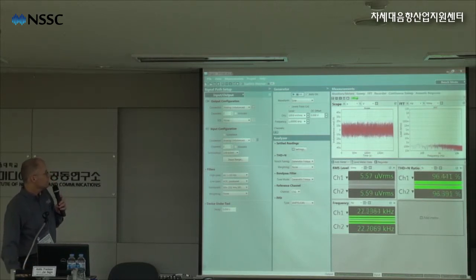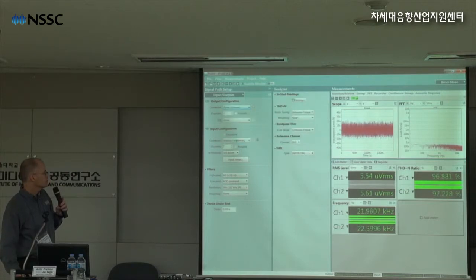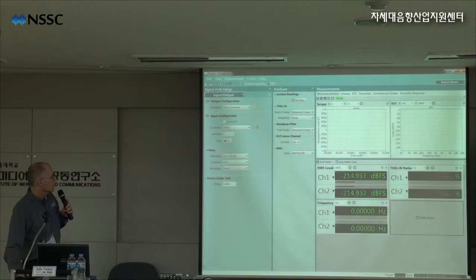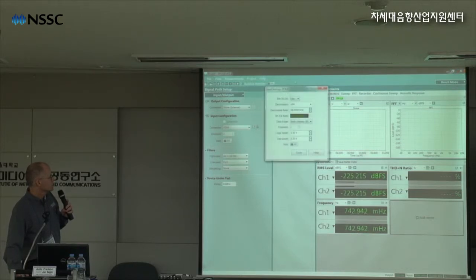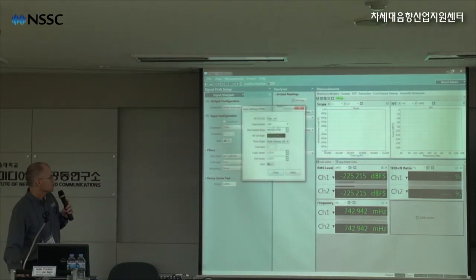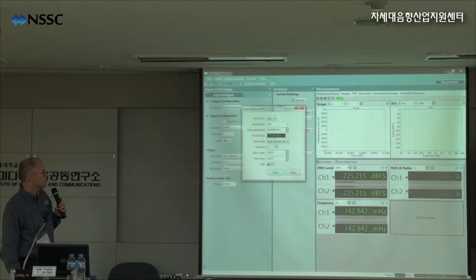Okay, so just open the analyzer in bench mode, and let's see, I'll just use no output for now. And on the input side, I will choose PDM. And this will bring up the PDM control panel. So the bit clock direction is out. The default decimation ratio is x64 with a 48 kilohertz sample rate.